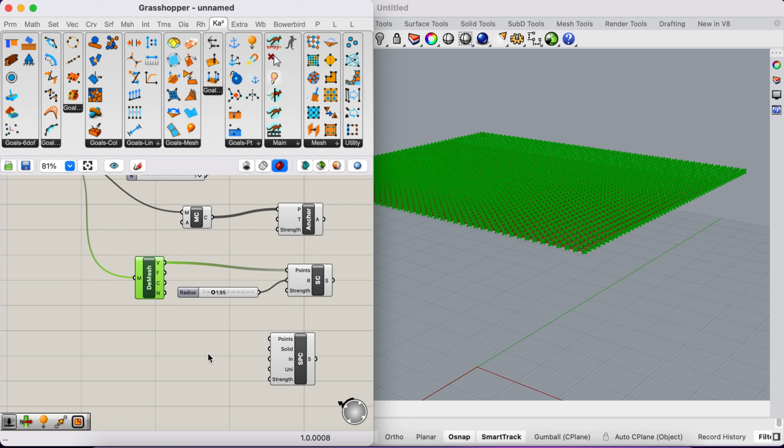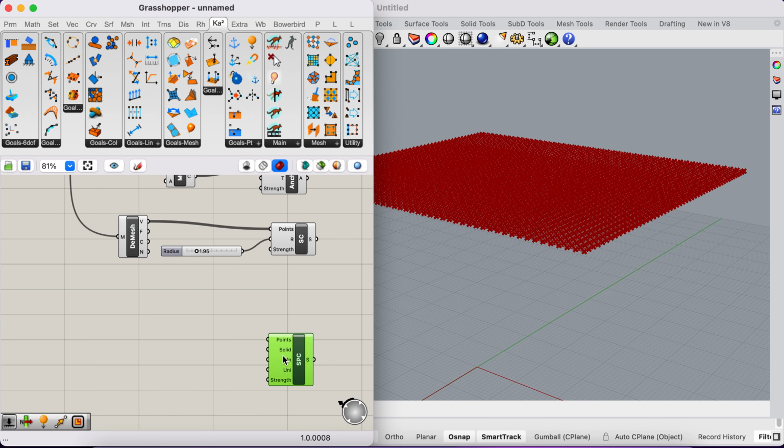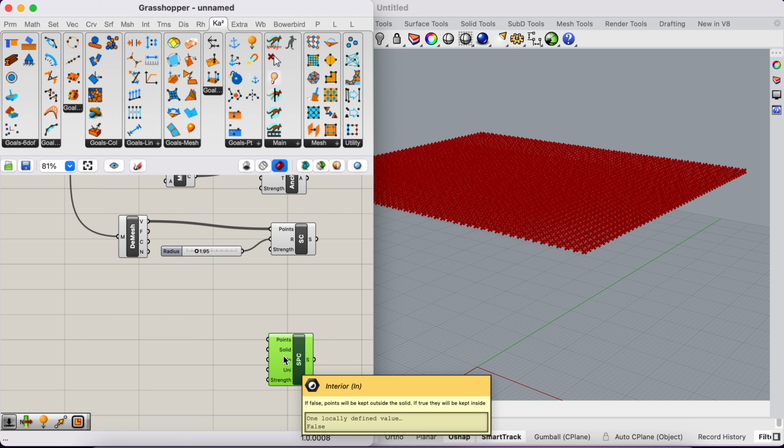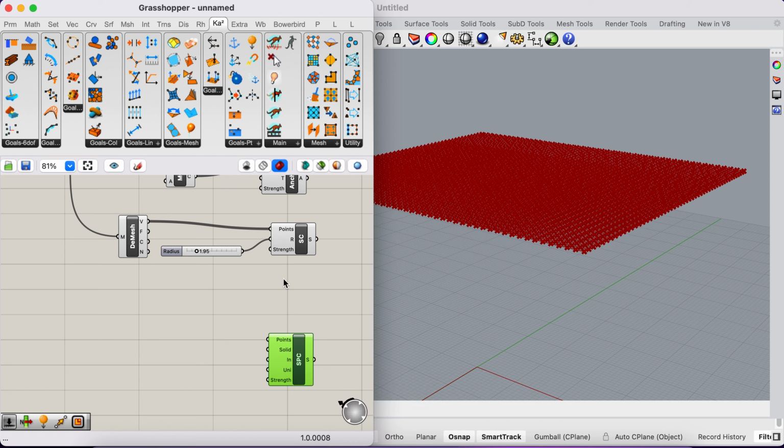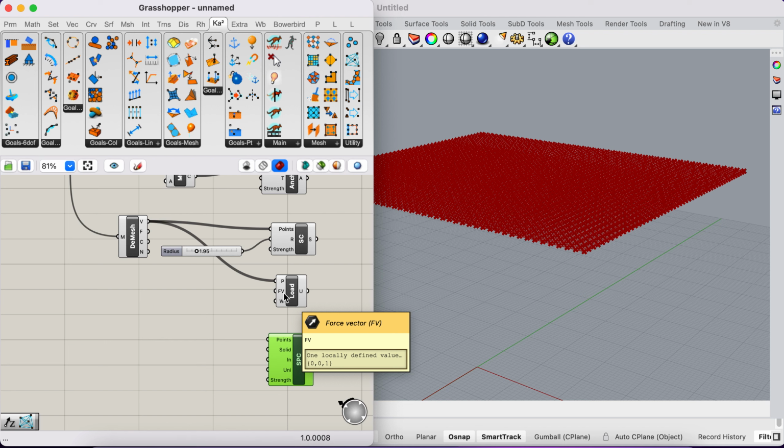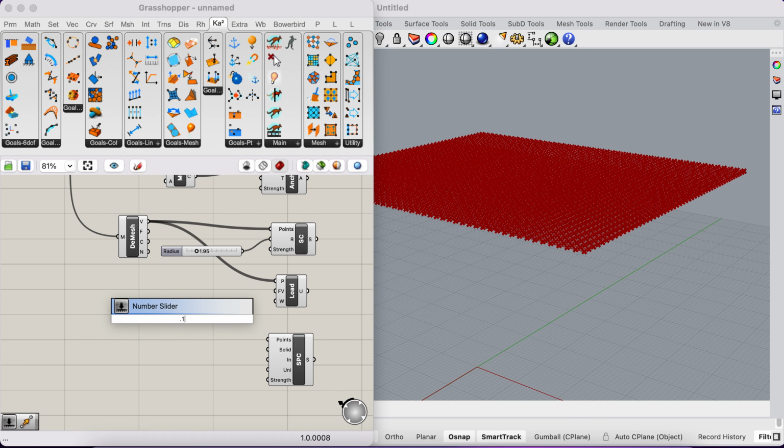All right. Now, we know that these points, in addition to being part of the simulation, have to have loads on them, right? So we need to bring loads in as well. So we're going to use the load, put the loads here, and do the same thing. The vertices go here, and the direction will be the z value, and the value for that is going to be 0.1.